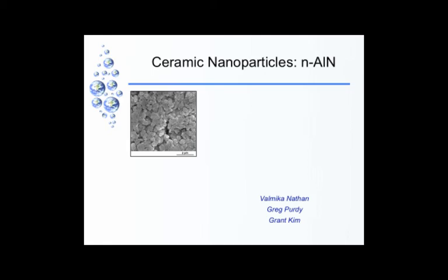We wanted to try to use nanoscale aluminum nitride mixed with microscale aluminum nitride. So bimodal, right? Large particles, you fit small particles in the middle of them, right? And then you see you increase the packing density. Because microscale aluminum nitride itself only fills to about 52 volume percent of space.